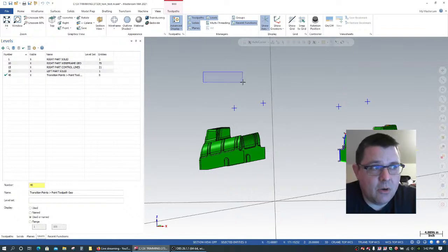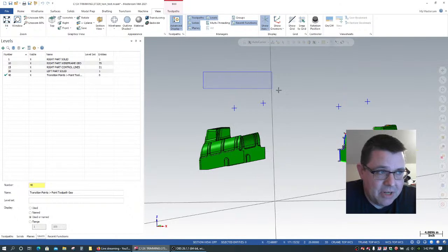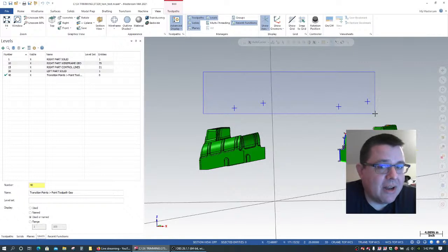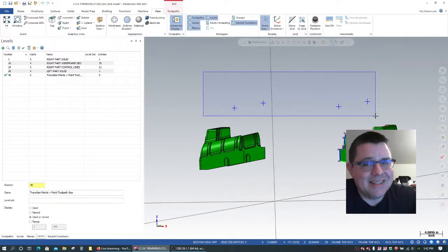So I'm going to left click and hold, and as I continue to hold my left mouse button down, I'm going to drag it to the right and down. And what happens is Mastercam starts to generate a selection window. And anything that is inside that window, contained within the perimeter of the window itself, like imagine the square that you see for my webcam, right?